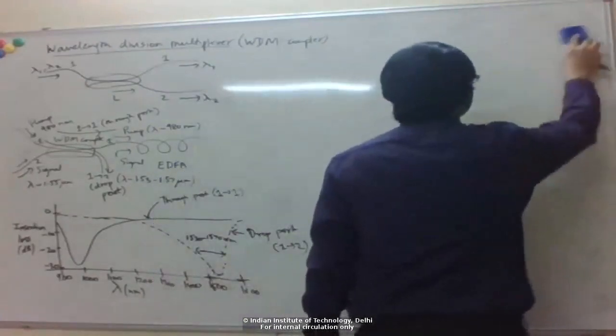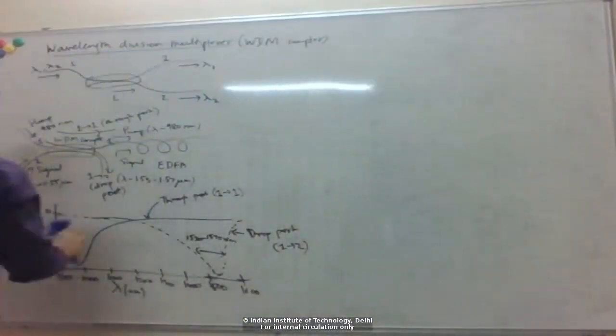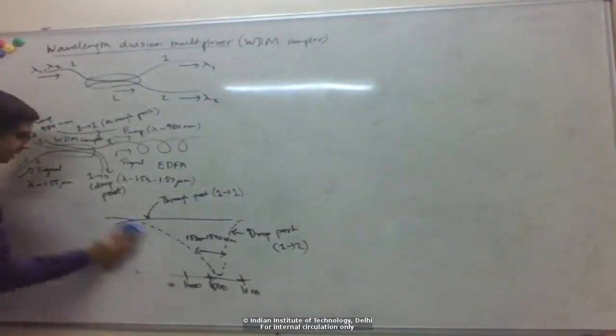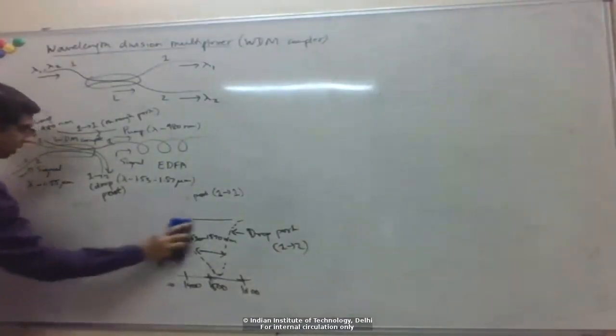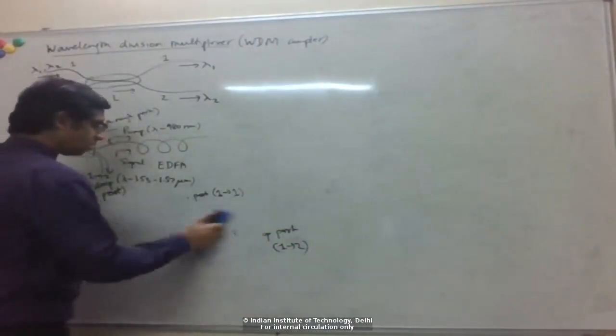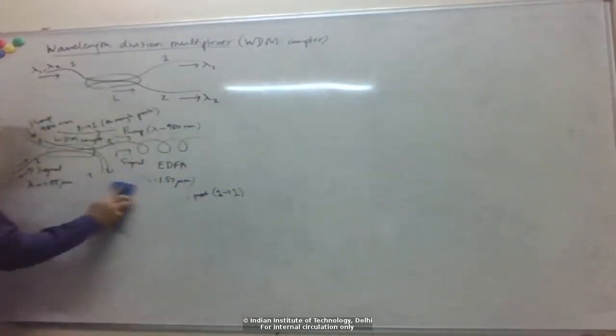So for communications, for example, that leads to polarization mode dispersion, which needs to be compensated for. There are devices called fiber polarization controllers, which you can use inline to periodically compensate for this polarization scrambling.